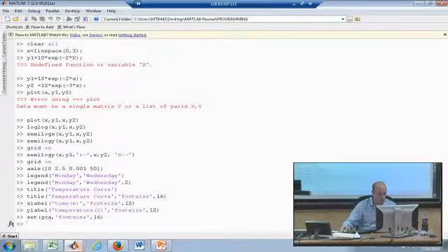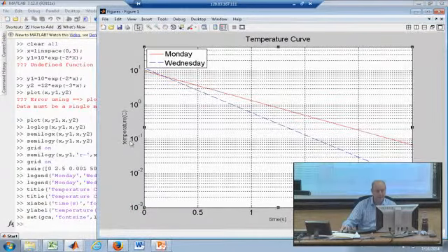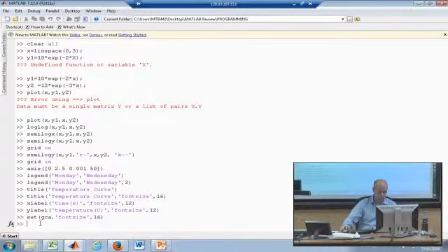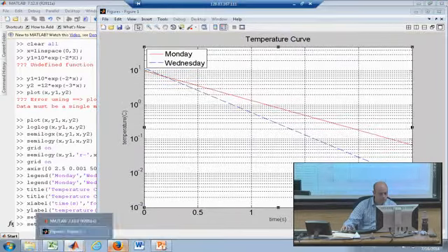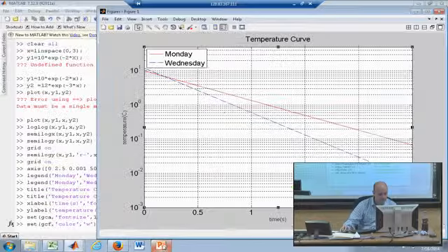All right. One other thing I don't like in MATLAB plots is the gray background. So I'm going to set, not GCA anymore, just GCF, get current figure, and I'm going to make the color, let me see if that's right, I'm going to make the background white. Yeah, exactly what I thought.